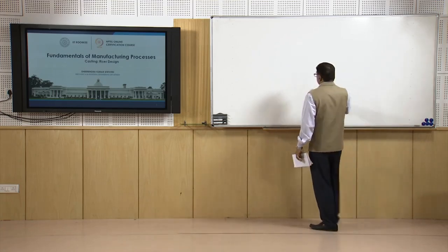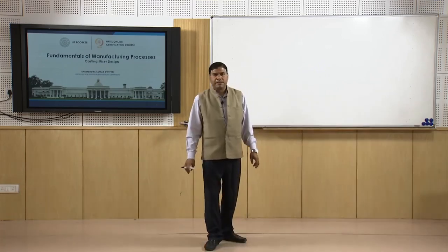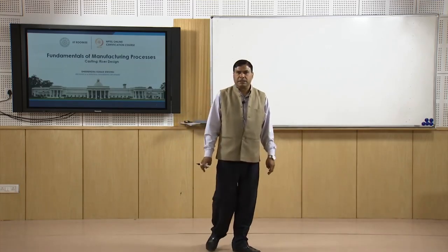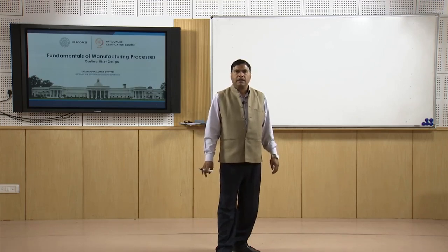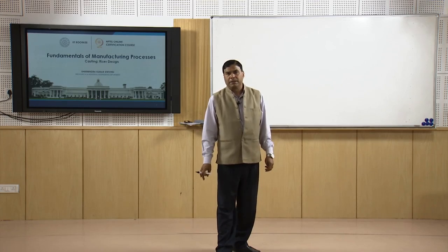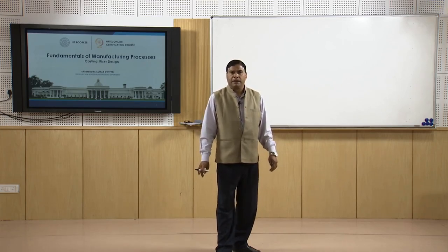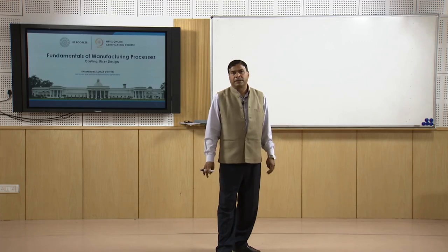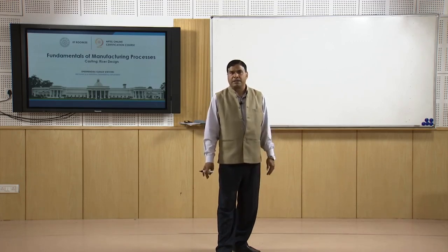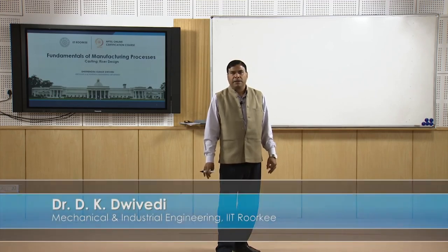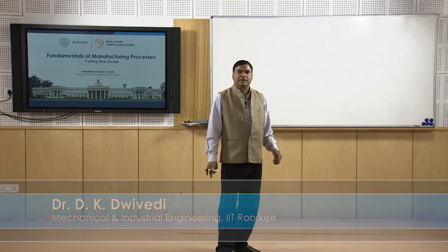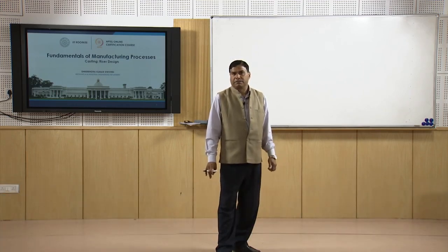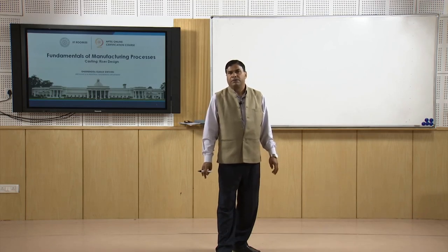So, now I will summarize this presentation. In this presentation, I have talked about two methods related to riser design. One method is Caine's method and the other is the modulus method, and in both cases we have seen that the cooling characteristics of the casting and of the riser play an important role in ensuring that the molten metal in the riser solidifies after the solidification of the casting. Thank you for your attention.